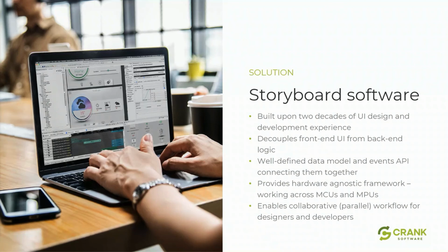One of those key cornerstones is the ability to decouple the front end, the UI, from the back end logic. So this is a state machine that's actually working the device. This could be spinning motors, turning lights on, heaters, whatever. The ability to decouple comes in two stages. The first one is it allows you to develop on your desktop and simulate and test the user interface on your desktop, and also it allows you to separate the logic, the control and the UI into separate worlds, really.